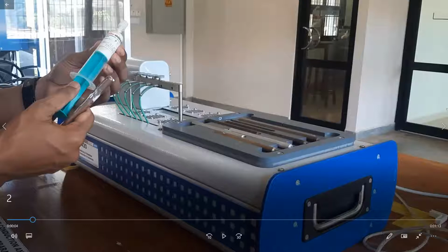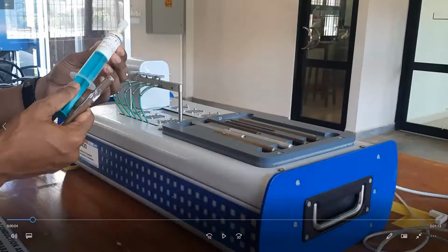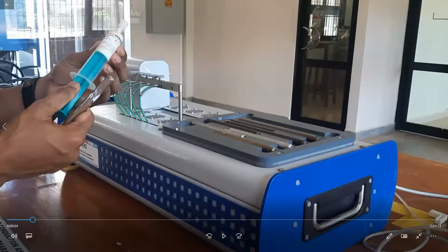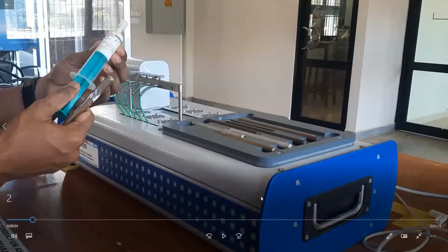In one side there is another hole to fix with the heater. There we also have to put some thermal paste to make sure there is no air inside the holes, and only conduction is happening, because we are testing conduction here. We should make sure there is only conduction inside the rod.